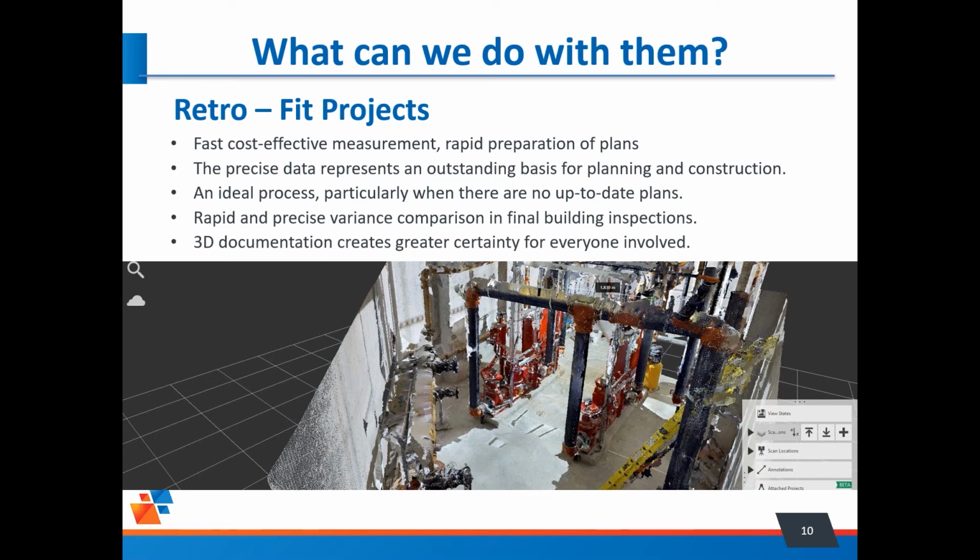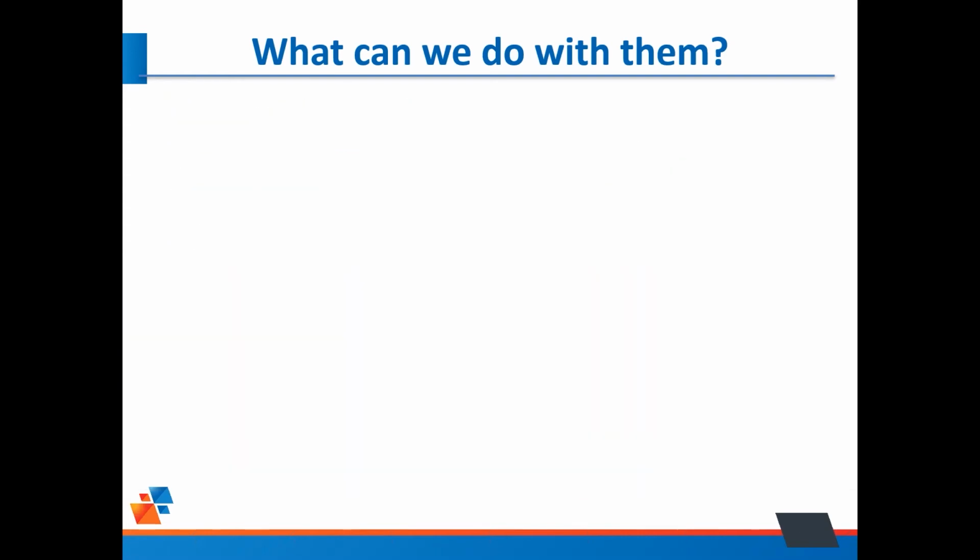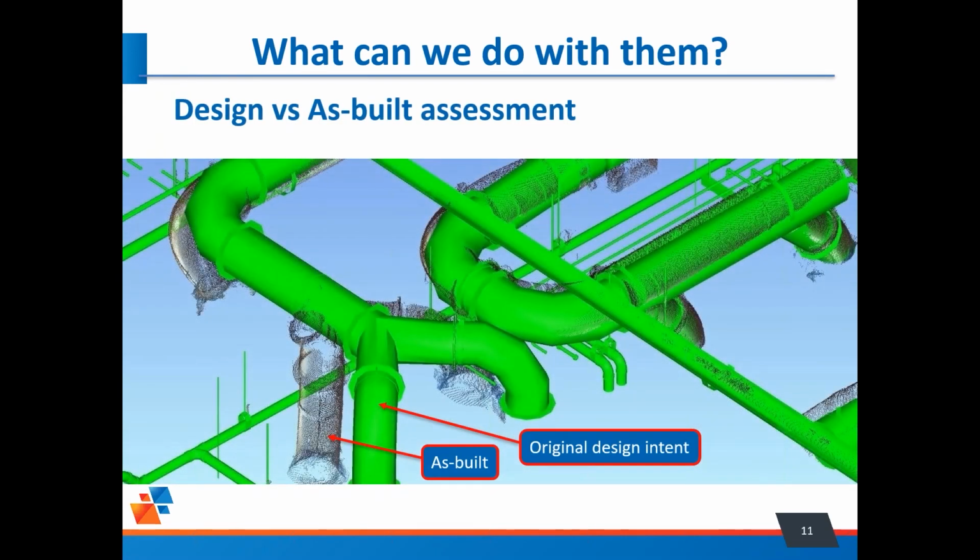3D documentation, obviously taking this information and putting it into any of your current CAD software and being able to use that point cloud. Another thing we can do with it is assess the design versus what was built. You know, scan at the end of the project, see how it relates to the original design intent, make necessary changes to create your as-built conditions, and then deliver it to the owner as your as-built.